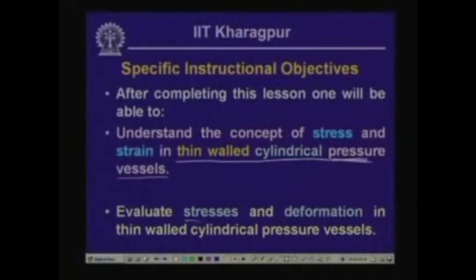Secondly, this is a thin walled vessel, and this term has a meaning: the thickness of the wall is very small, so that the stress variation across the thickness is significantly small, or we neglect that. Hence the thin walled pressure vessel is of importance, and we will look into how to compute the stresses in such vessels, and thereby evaluate stresses and deformation in thin walled cylindrical pressure vessels subjected to internal pressure because of the content in the container.